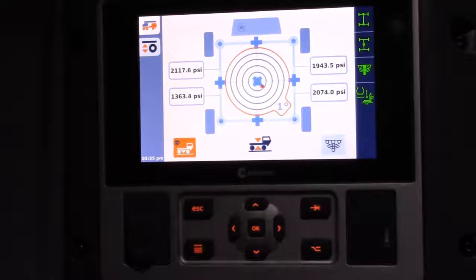And again, this is not saying the crane is level. This is looking at the midpoint of the 4 struts, 2 on the very front, 2 on the very rear, looking at the proximity switches in those struts to know that we are at the midspan of the strut stroke. Now we could drive the crane down the highway, and of course we have to have it unlocked also to be in that condition.